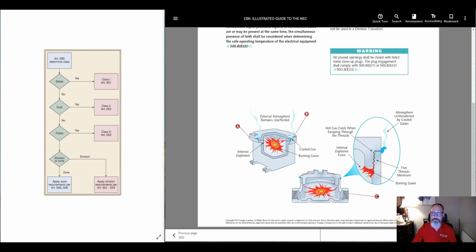The smaller boxes will be the screw-in ones, and your larger ones are going to have this flat flange on it. Now, the idea, and what they're trying to show you here, is that with the way this is installed, you contain the arc in the box.